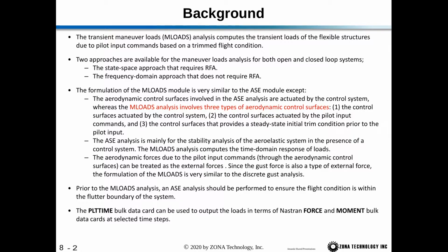The PLOTTIME bulk data card can be used to output loads in terms of Nastran force and moment bulk data cards at selected time steps so that you can perform some maneuver and then at selected time steps you can export the Nastran force and moment cards and then do a detailed stress analysis in Nastran, a static loads analysis at those specific time steps.